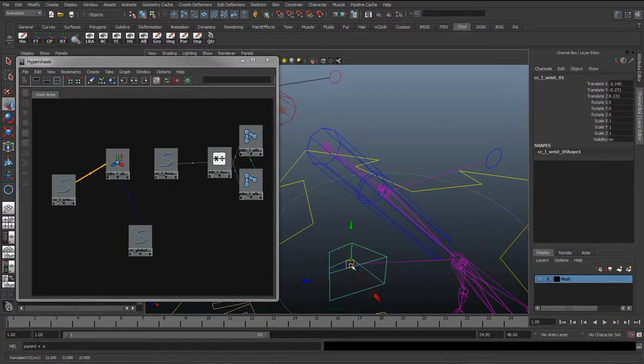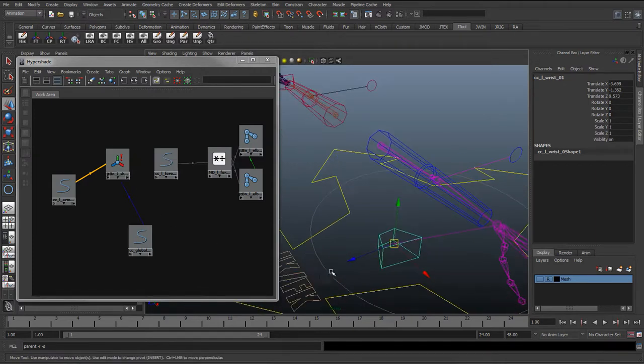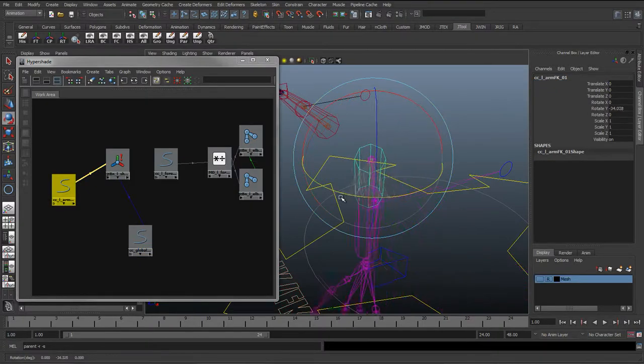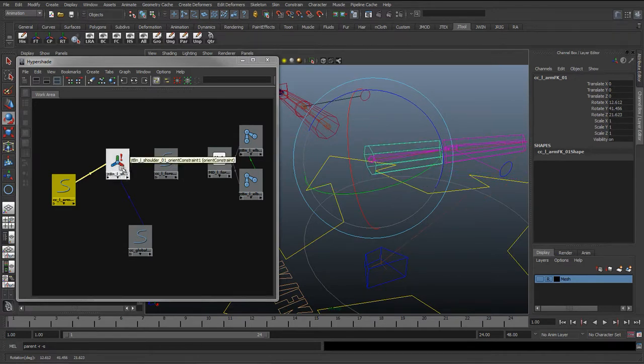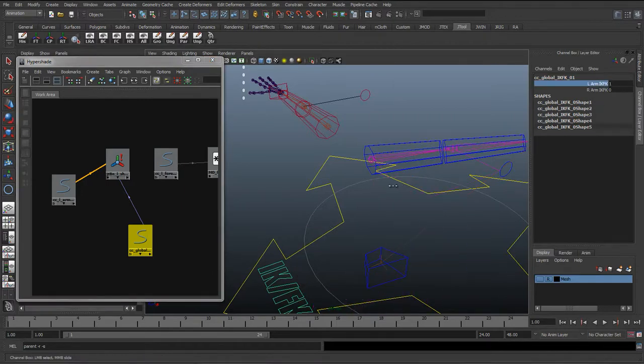So what we can start to do actually is, if I move this IK/FK control, this wrist control, select the IK/FK and start to blend this, you can see how now we're getting that nice blend between those two controls. And we can see if I rotate this back, the rotation's working, the FK control's working. So I'll rotate that up, setting the IK and FK control down here. You can see it's blending between those two. So it's switching the orient constraint off and switching the IK on. And the result of that is it's going to smoothly blend between those two values.